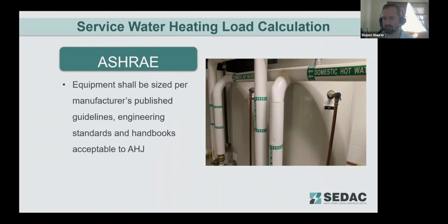For facilities such as the one pictured here, where there's a couple of storage tanks, you could try to isolate one or more to see if all the tanks are still required based on current operation. Usually when new water fixtures are installed, they're going to be using less flow than previous fixtures. And so if you're renovating a building that has multiple water tanks, you may be able to get away just by isolating a storage tank that's not needed.